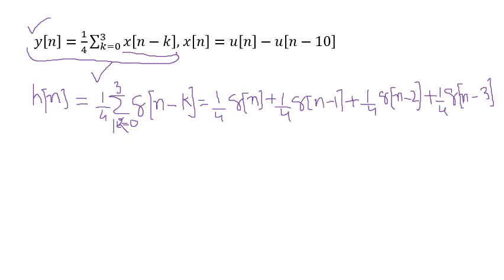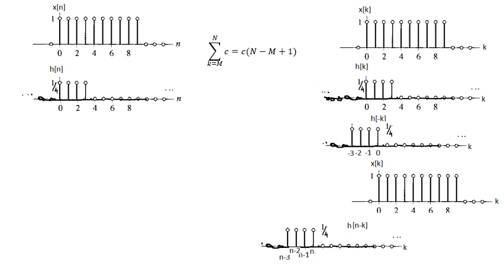So now we have both the impulse response, which is this one, and the input signal, this one. So the first step is to plot the two signals versus n, so you understand this is the impulse response and we also have the input. So let's see how. By plotting the input signal, because it is mentioned that input signal equals u of n minus u of n minus 10. Okay, so what does it mean?